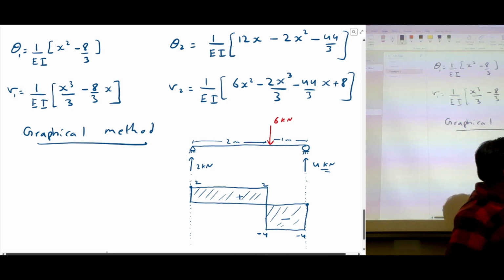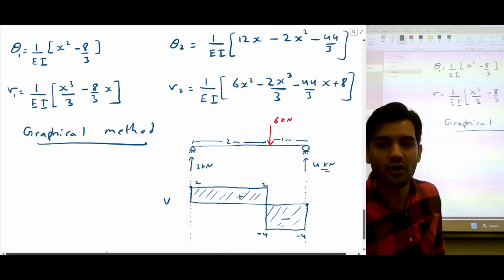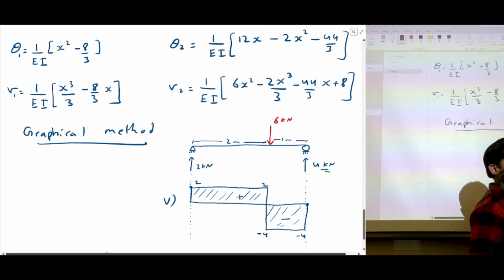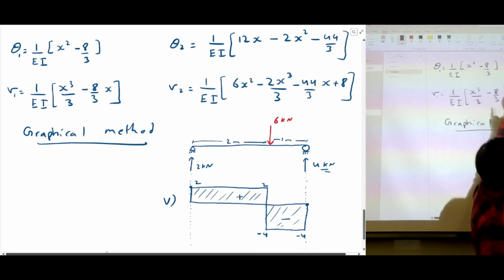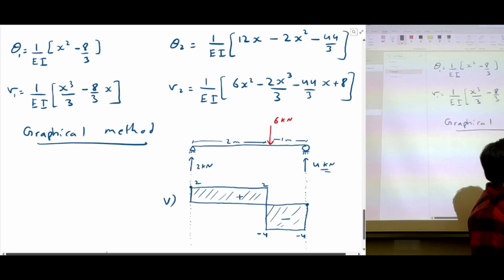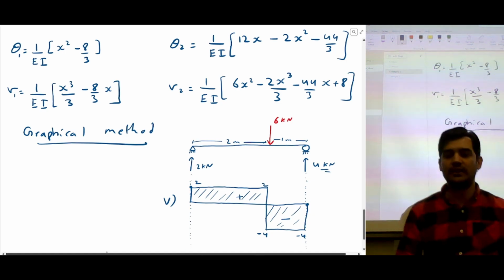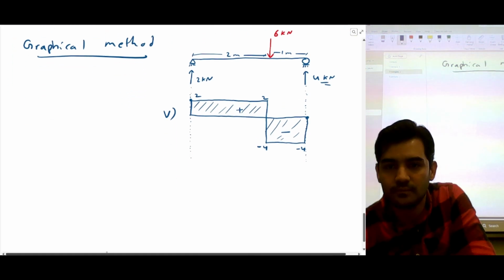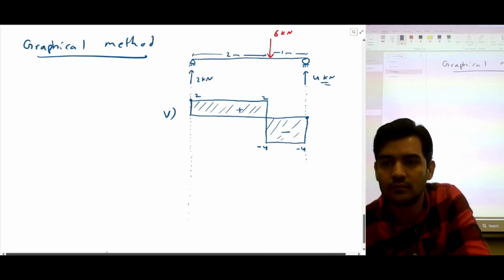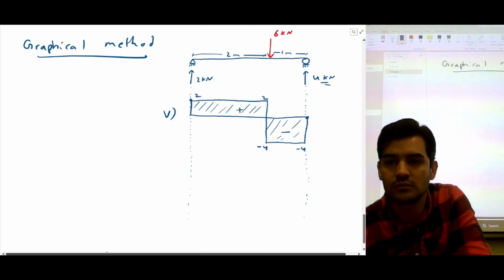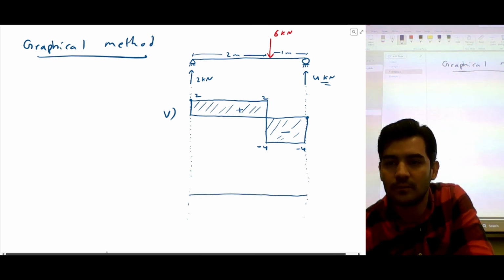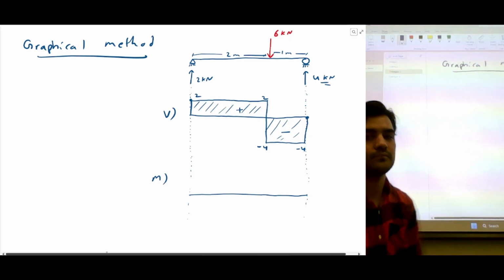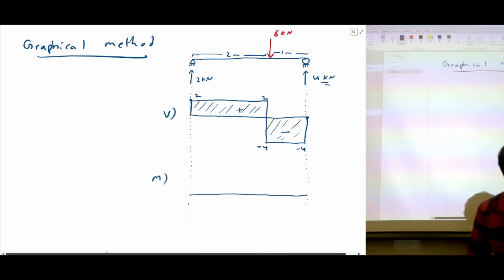So yeah, from the shear force we can draw the bending moment diagram as well. We can also use the equation, but we can also use the integration of shear force. So what we're going to do is integrate the shear force and calculate the bending moment diagram from the shear force directly. So now we'll draw the bending moment diagram. The integration of shear force is bending moment, right?